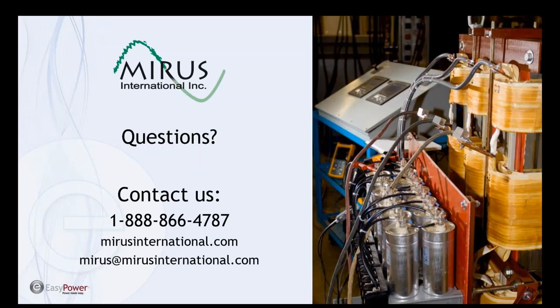If you are tuned above the 5th harmonic, say above the 7th harmonic, and you add the power system inductance, your combined resonance frequency is going to move down, and it could move to the 7th harmonic and create a resonance with the harmonics that are present on the power system. So an excellent question, and it makes a lot of sense. If you are putting in capacitors to deal with the displacement power factor, you do want to consider detuning those capacitors to a harmonic number that's below the 5th.